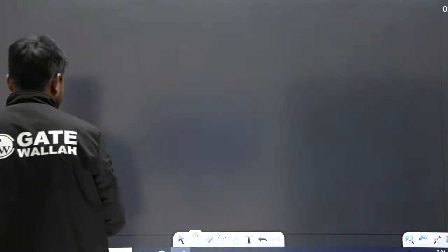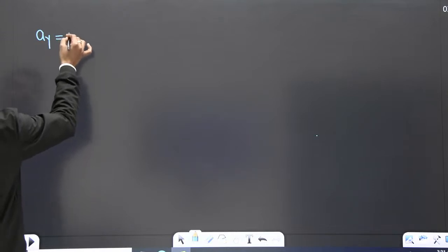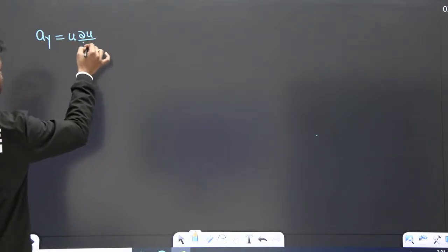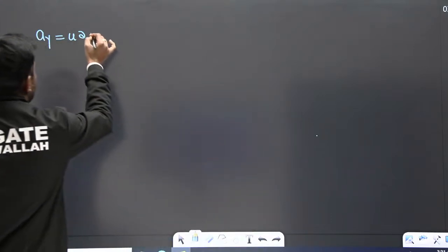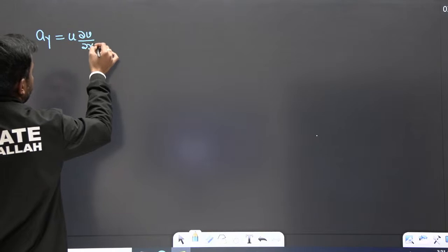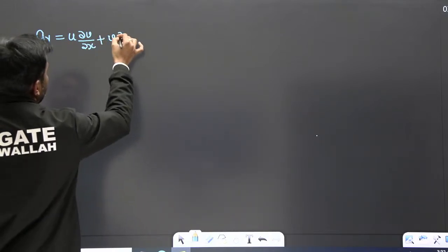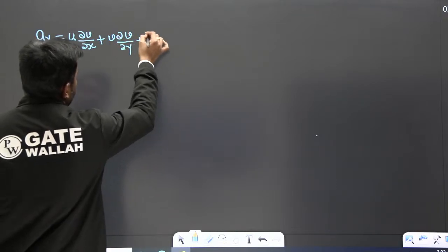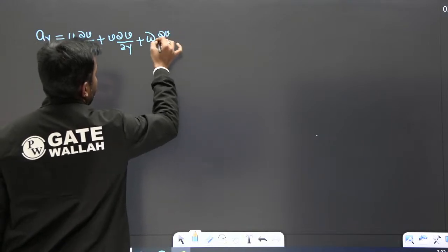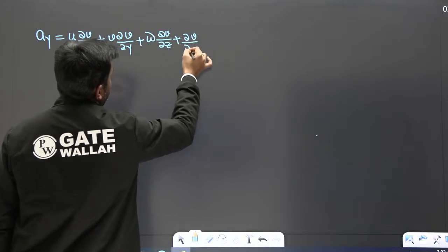So the y direction acceleration will become u del v by del x plus v del v by del y plus w del v by del z plus del v by del t.